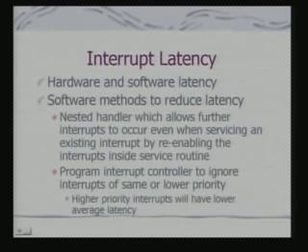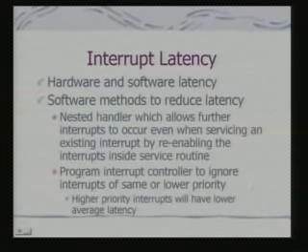Okay. And obviously, in this case what will happen? The interrupt which is now raising a request need not wait till servicing of the previous interrupt is completed. And when we are using an interrupt controller, we can associate different priorities with the devices. So, what can happen is that a higher priority interrupt can actually interrupt the service provider of a lower priority interrupt.